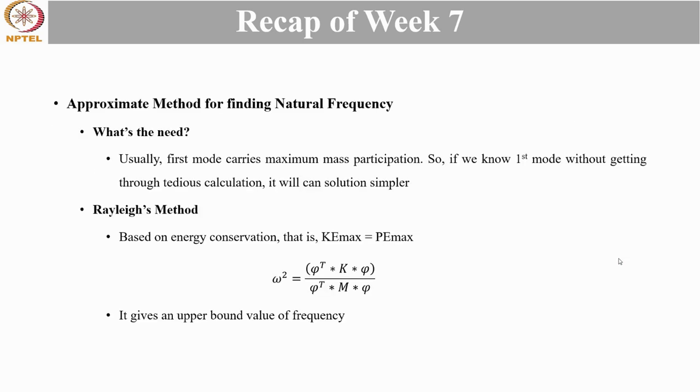We also saw some approximate methods for finding natural frequency for the first mode of vibration. Now, what's the need of these? Usually, the first mode carries the maximum mass participation. So, if we know the first mode without going through the tedious calculation of matrix solution, it will be a simpler solution.